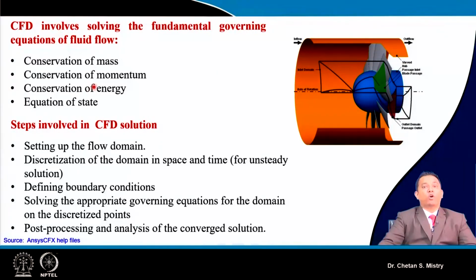Okay. Now, in order to do CFD analysis, there are certain steps that need to be followed. Here, if you look, this is a fan. In order to simulate or analyze this fan, we need to make the flow domain first. Suppose I have a larger number of blades or a larger diameter of the fan; under that configuration my computational requirement will be huge. At the same time, the analysis will also take a large time.